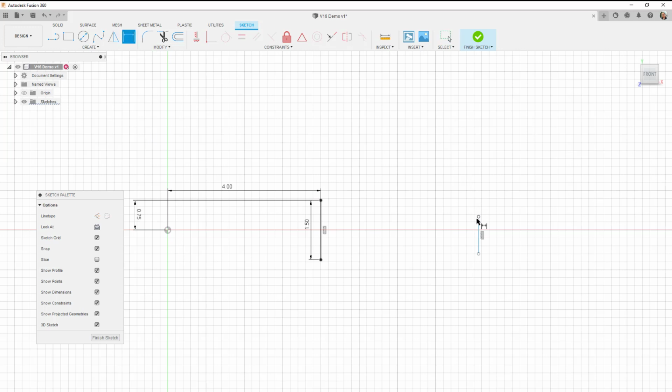So then let's start dimensioning the other one. At this end of the model, the thickness is, what did I say, ½ inch, 0.5. And then we'll again dimension from the origin to there. And that dimension would be 0.25. There we go. And then it is out at 20 inches. All right.